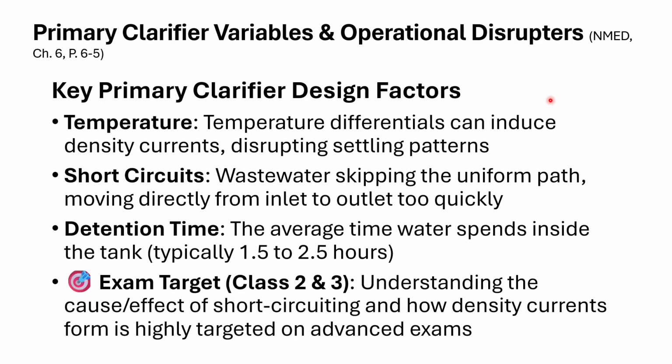So here are some design factors for clarifiers that you should understand and be able to discuss. If you can do that, you're going to be able to answer the questions on the certification exam. With temperature, recall that in chapter 3 of the Ragsdale manual, we said that temperature differentials can cause density currents. They can disrupt settling patterns. What it means is you're going to have a different flow pattern within the clarifier if there's a wide variation of temperatures.